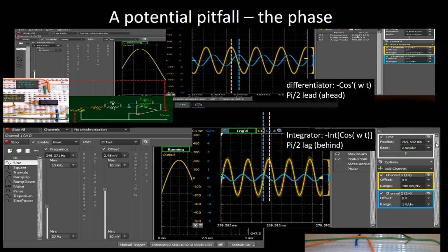These phase relationships are valid over a wide frequency range as shown in the data, and deviate only for the extreme ends where the op-amp finite bandwidth has effects. Thus, erroneous measurements, including connecting the scope leads to wrong nodes, or parasitic capacitive coupling effects can be caught early if these basic features are used for sanity check.